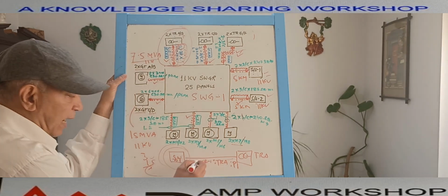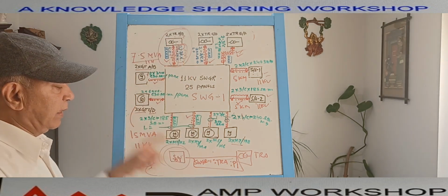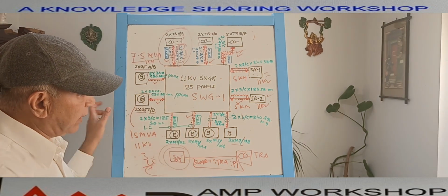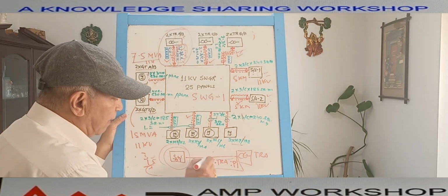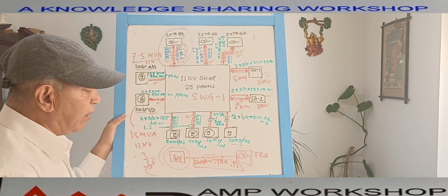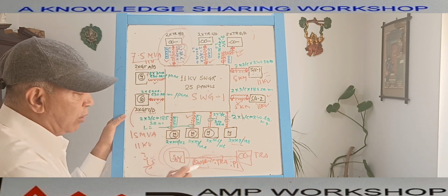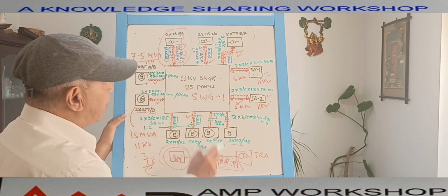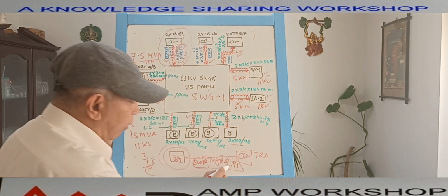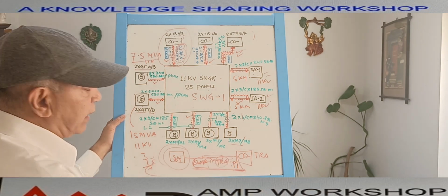So from this tag, we can make out, if we see a cable in the field and this cable tag is provided over the cable, from the tag I can immediately make out this cable is coming from switchgear 1, that means this 11 kV switchgear, and going to transformer A. Transformer A is this, and the cable number is P1. So we can easily identify this cable tag.